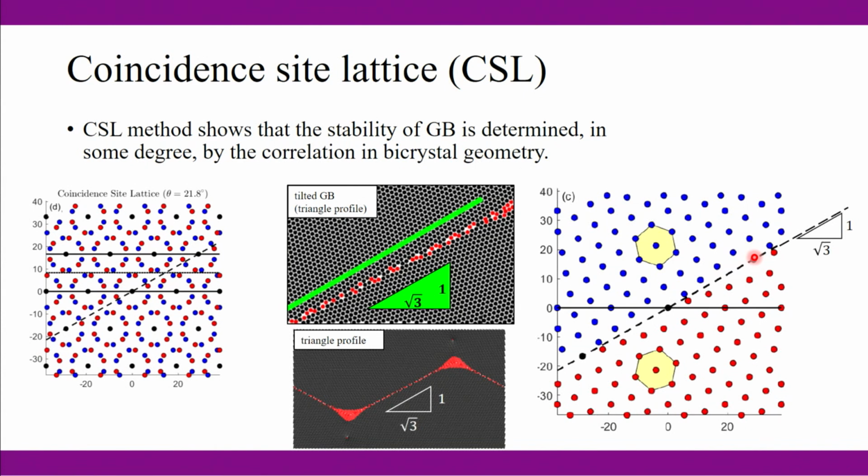So although in the very beginning we are seeing a rather sinusoidal wave, as the system can explore the region, it can find the other coincident site lattice plane and align in that direction because it is energetically less costly. So again, you are seeing the PFC can capture this CSL property very nicely.